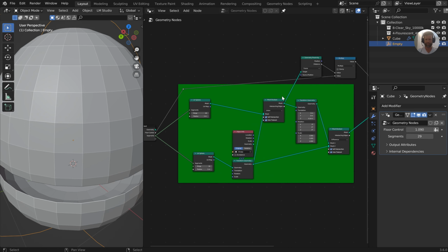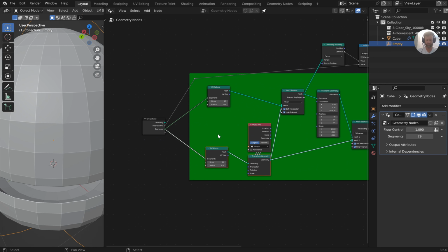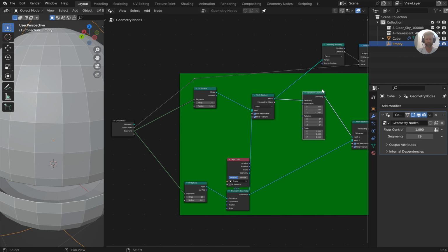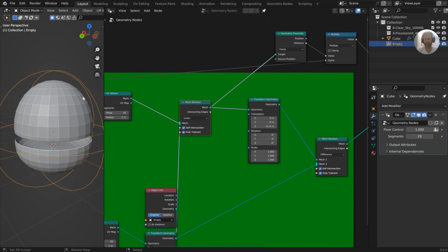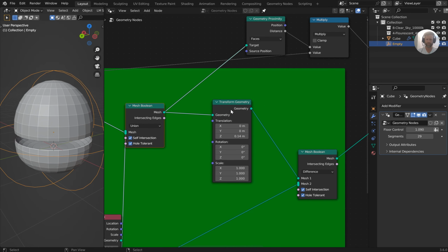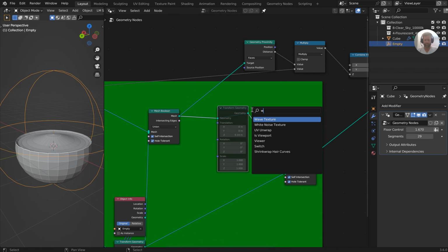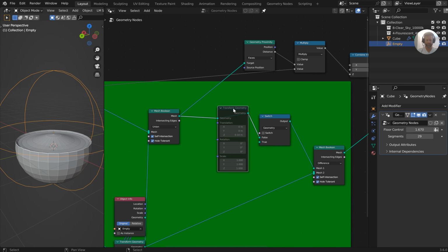All right, I'm all about making things procedural and as non-destructive as possible. So let's clear a little space here. And what I want to do, if you hit T to get rid of this, that's so annoying. If you don't want the top there, if it's annoying perhaps, you can grab the transform and hit M to mute that, and everything should work as usual. Once you get into extruding things a little bit more, you may get a little bit of a problem, but if you want, you can throw in a switch for this, and I'll just turn it back on.